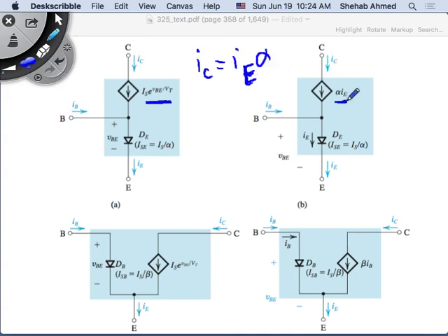And this one is similar here. So I have forward biased the base emitter junction. This current is summing up into IE with IC. What is IC? IC is equal to beta times IB, right? My other equation is IB is equal to IC over beta.